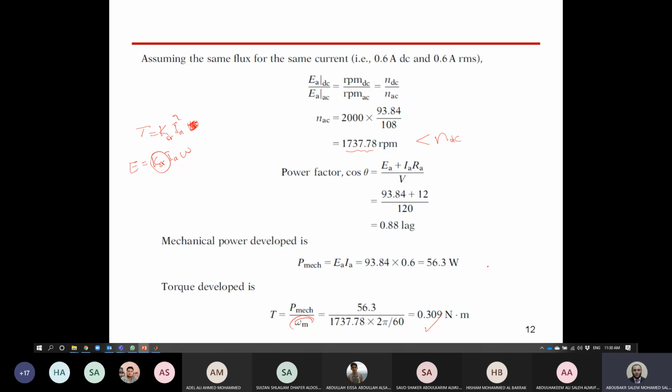By the way, we discussed that universal motors are used for domestic applications which need high starting torque. For kitchen machines, you always load the machine first, then apply the supply to the motor, so you have a high torque and it needs high starting torque. For that we prefer the universal motor for high starting torque applications, like drilling, for instance.